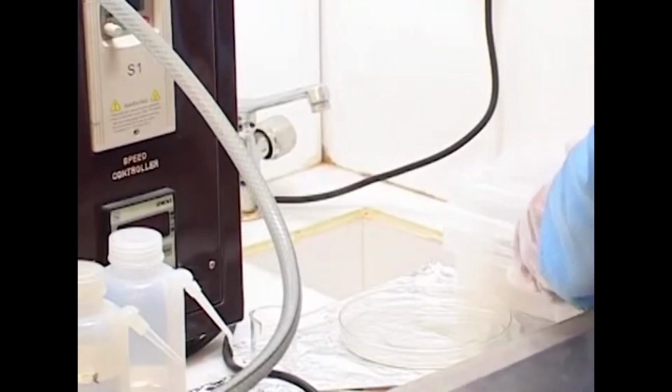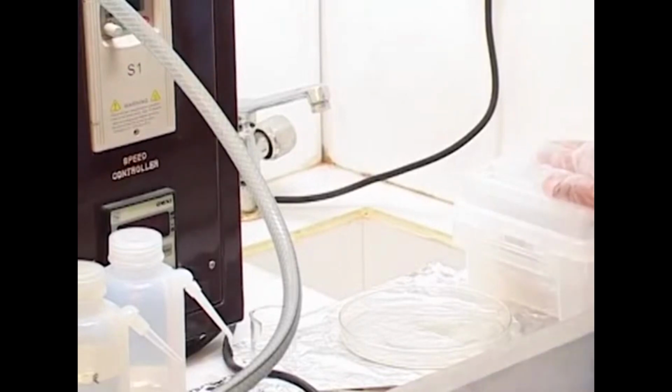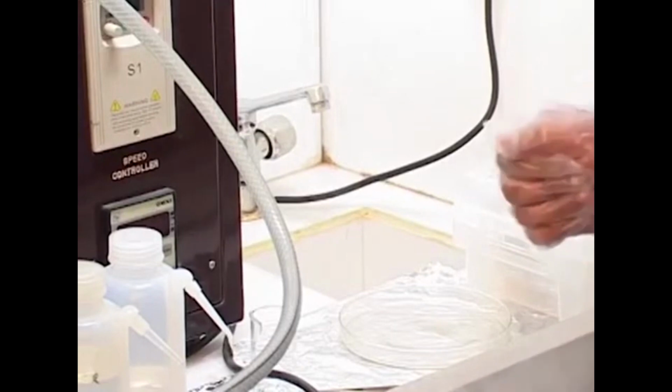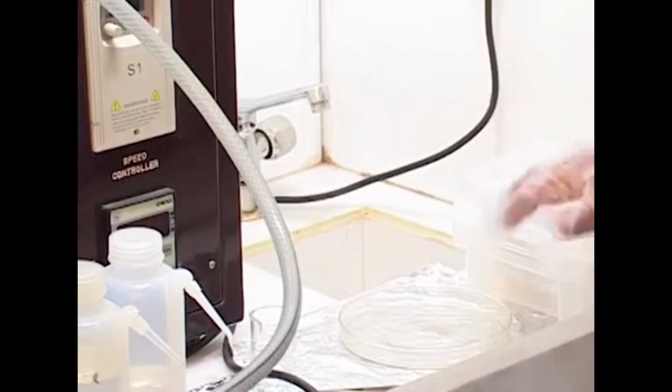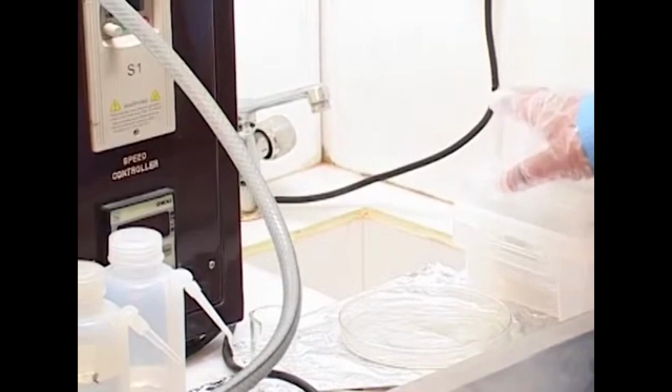One of the reasons is that we have to be extremely careful while handling silicon wafers, because they are very fragile and essentially can crack even on little impact or stress. So we have to make sure that this wafer box is far away from the experimental setup, at least the main box is far away from the experimental setup.